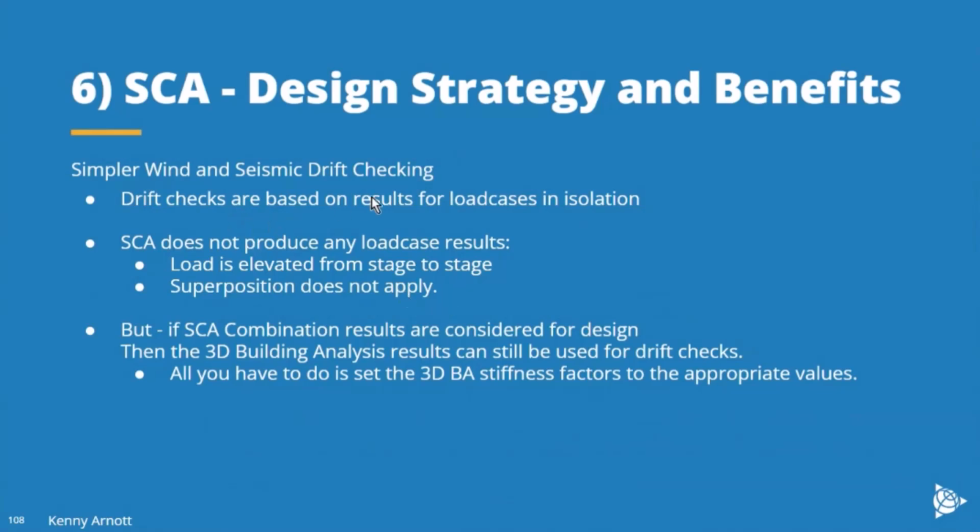So the drift checks are based on the results from load cases. Those don't come from a stage construction analysis. But alongside doing the stage construction analysis, we continue to do the 3D building analysis in the unstaged version of it. And so we can still use the results from that specifically for the drift checks. And all you have to do is set the 3D building analysis stiffness modifiers, because you're now not relying on the 3D analysis for design. You can set them to the values that you feel are appropriate for the drift checks.